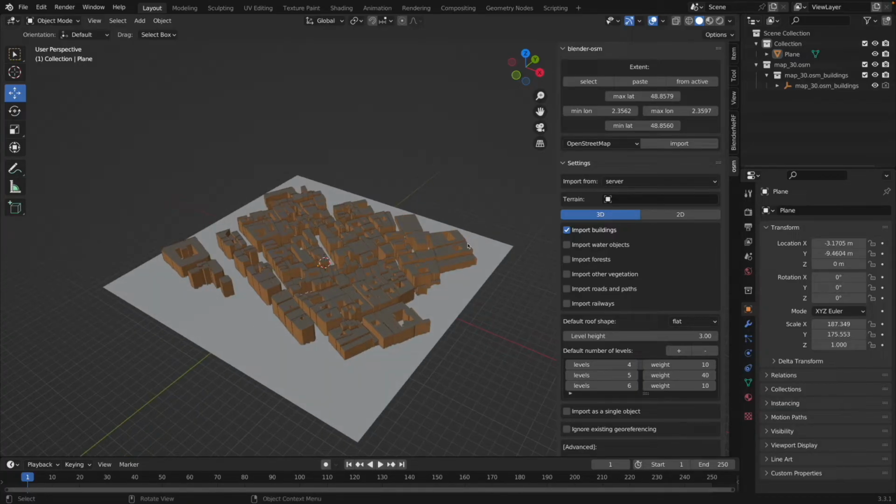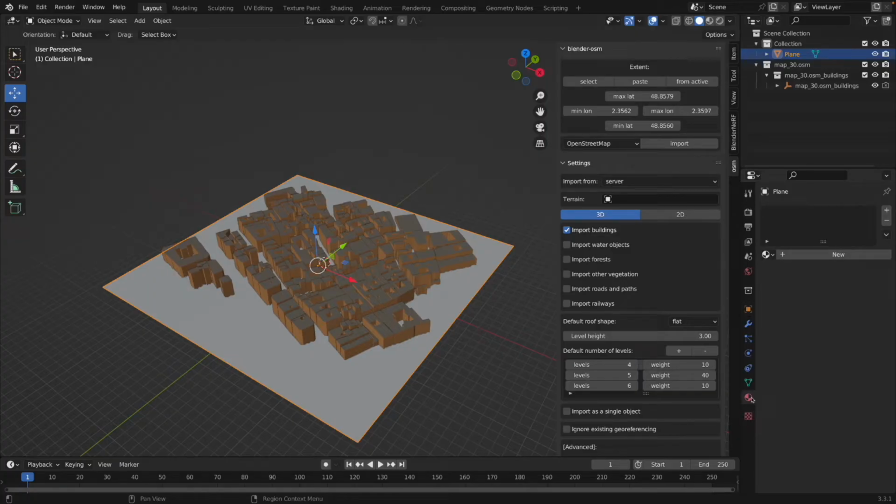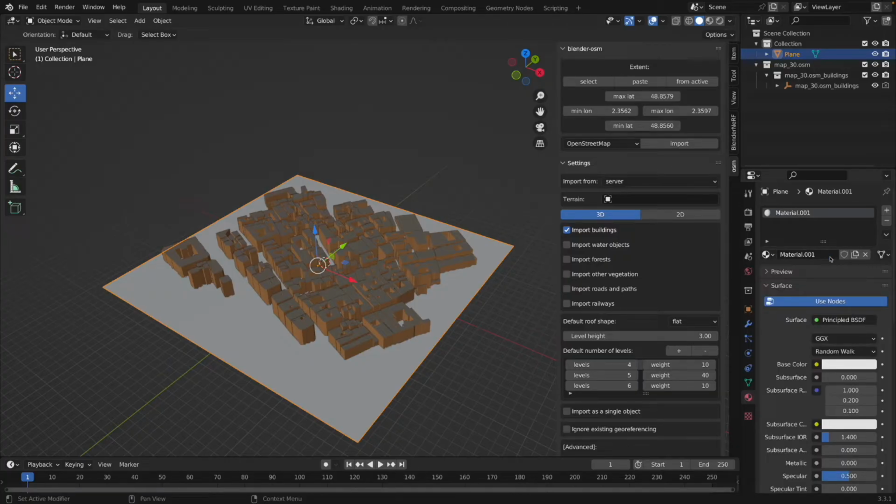Once the geometry is set, we need to assign radio materials to the different elements that make the scene. By elements, I mean objects. Let's start with the ground plane. We first select the ground plane here, and then go on the Material Properties tab. As we can see, there is currently no material created for this ground plane. So let's create one by clicking on the New button. Blender creates a default material with a default name and some default properties for rendering. These properties here are for rendering.